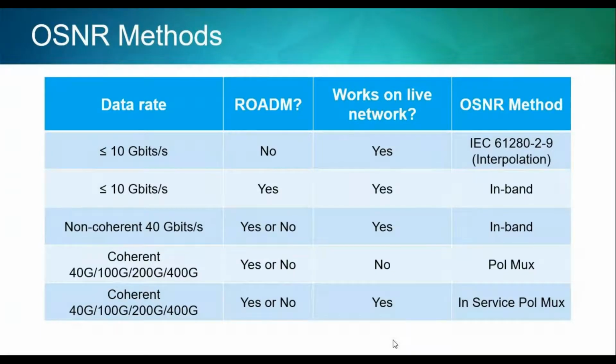All right. The IEC method is very straightforward, very simple in its use, and the OSA itself will tell you if there's a problem and which method you would need to use, right? So there's already intelligence in the system with regards to that, but there are no adverse issues of using the in-band method across those systems, with or without the presence of a ROADM. So okay, would the in-band method be a good default method if your knowledge about the system is limited? Absolutely. Yeah. Okay. Good. Absolutely.